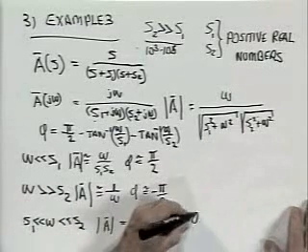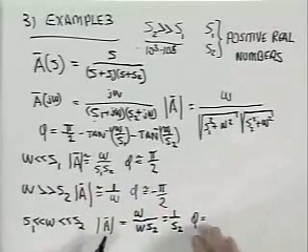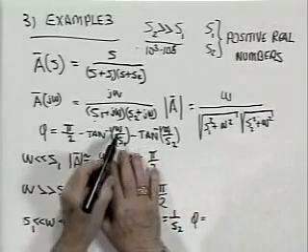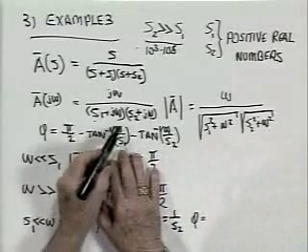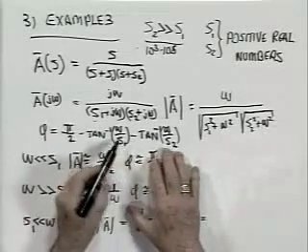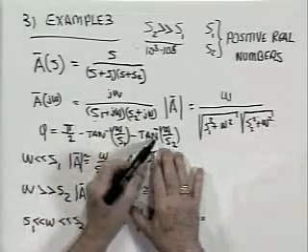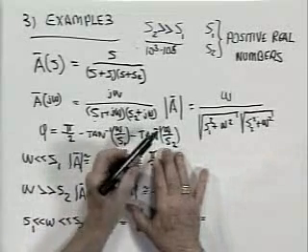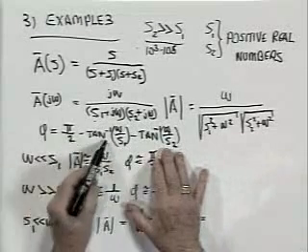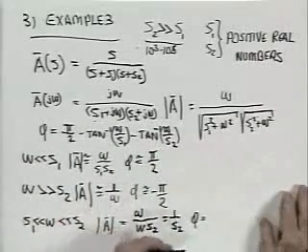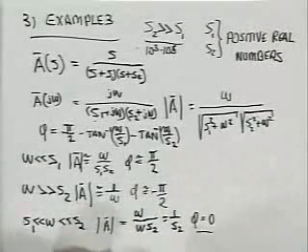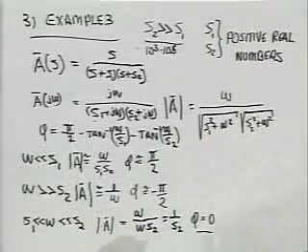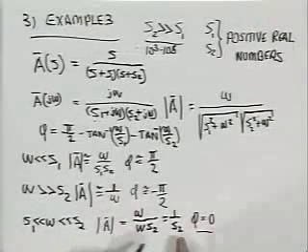And the angle, in this case, let's look back here. Now we said omega was large compared to S1, so this is the angle whose tangent is a big positive number. It's pi over 2. Omega is small compared to S2, so this is the angle whose tangent is small and positive. That's approaching 0. So it's pi over 2 minus 0. So phi in this case is just 0. We've got two asymptotes, low frequency, high frequency, and a mid-range with an asymptote and an angle.